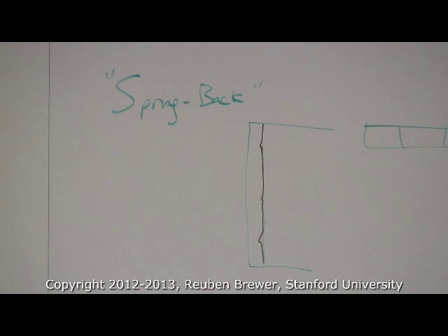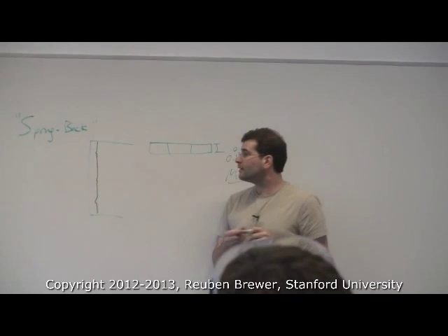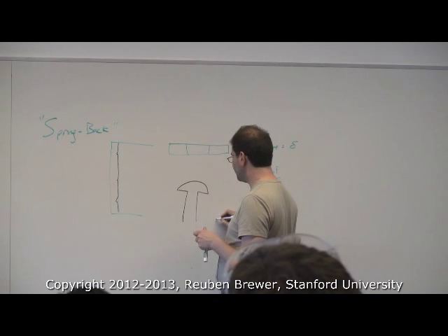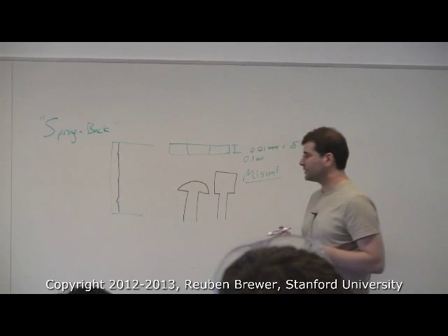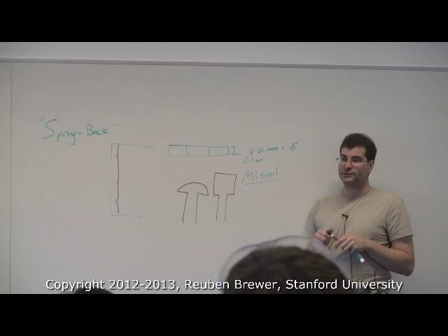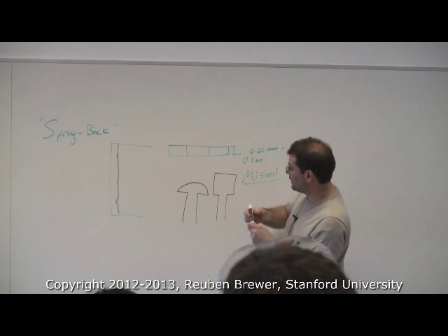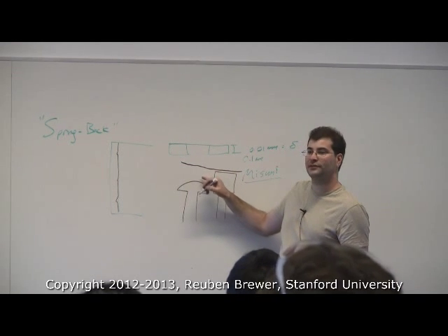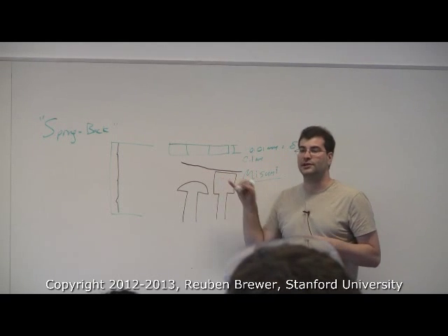Okay. Some of you used screws that were the incorrect screws. The ones for the rollerblade wheels were button head, and their profile was this. Some of you used ones like this. What's the problem with these, potentially? They stick out too much. So I think you guys got lucky. I probably should have designed it so it wouldn't have worked, but the bearing flange was right about here, and I gave you lots of clearance with the button head. That's why I used those screws. And here you could have either gotten lucky or not lucky, and it would have jammed up and prevented rotation.